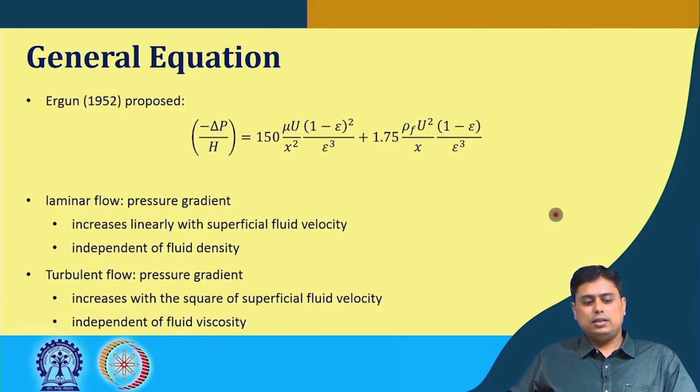So, this Ergun equation you can use irrespective of the flow region, and it is specially mentioned here that it is for spherical particles having a diameter of x. If the voidage is known, when single phase flow is happening, you can calculate its pressure gradient through a stack of mono-sized spheres.